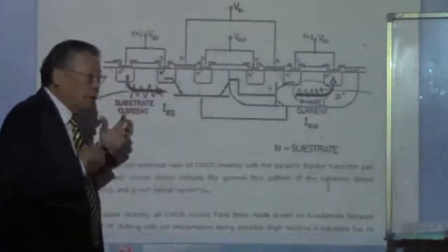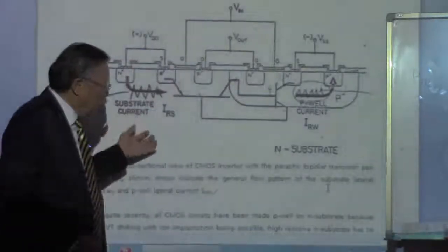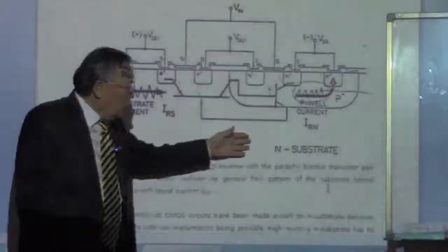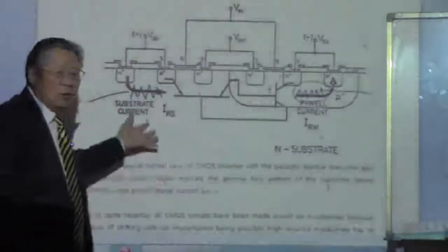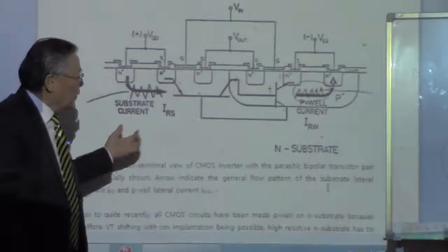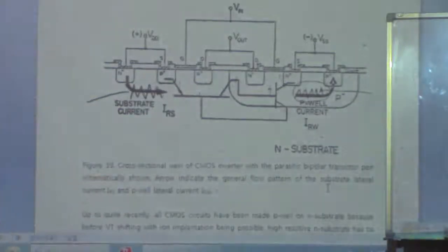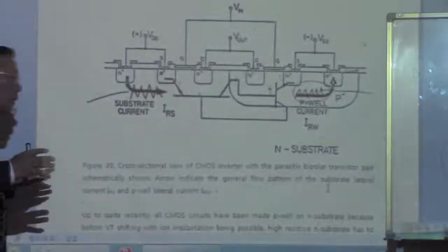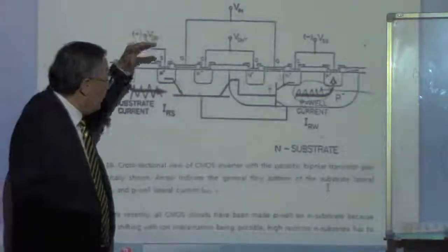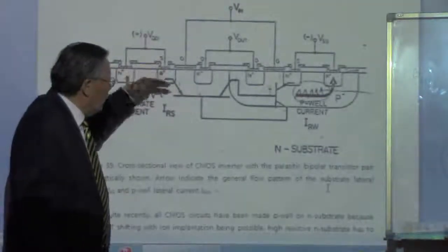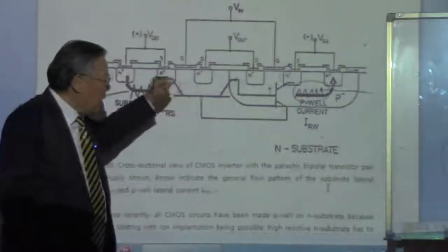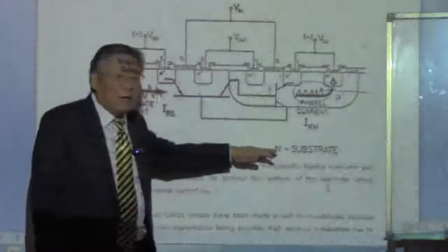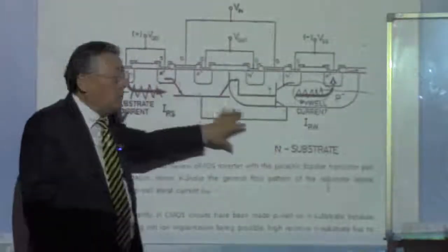But we have a high leakage current because of the damage to the whole device. That is a sacrifice. Okay, so latch-up can be prevented by reducing the beta in this lateral device, but we are going to have a high leakage current because of the damage to the substrate.